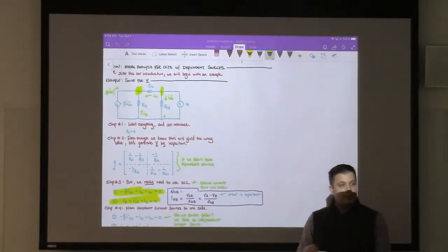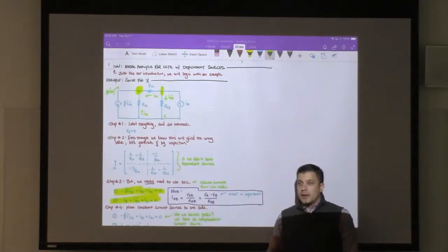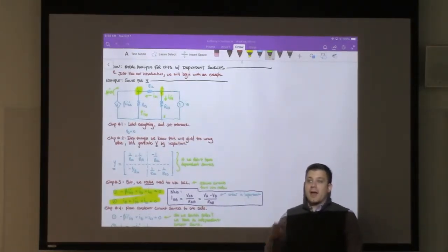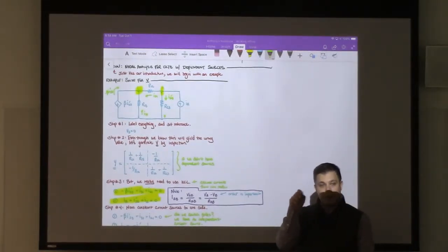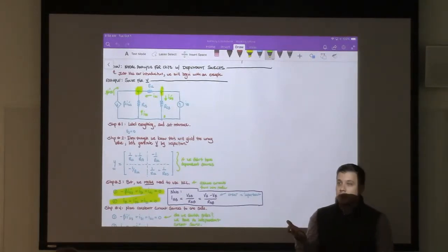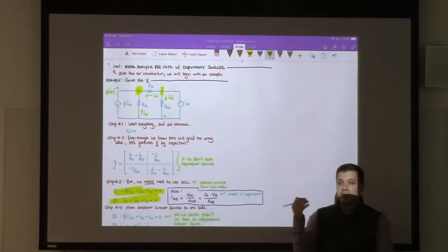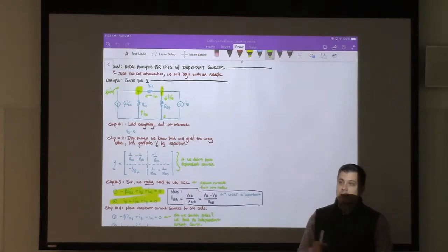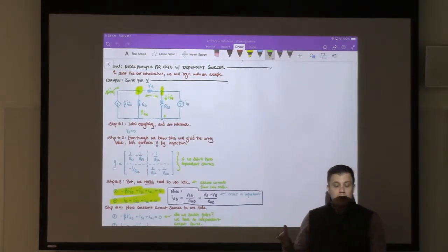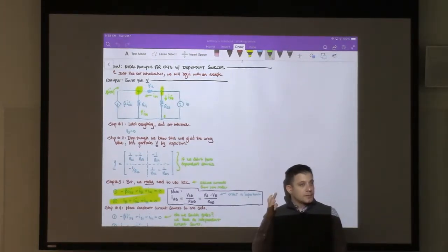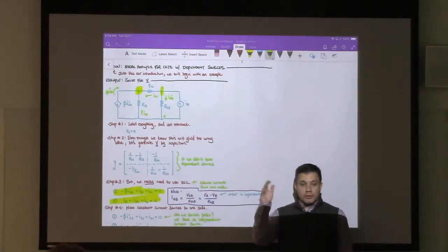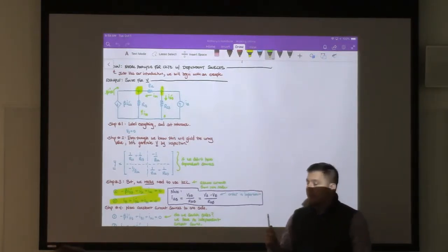If there is no resistance that connects the two nodes, then you would have minus 1 over infinity, because that's an infinite resistance between the two nodes, and that gives you a 0, which means that element is gone. The voltage array is unknown, so those will just be populated by the variables.